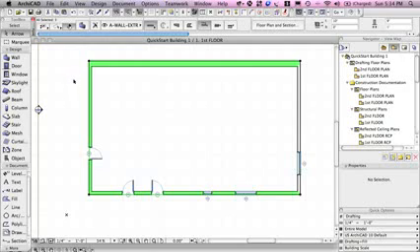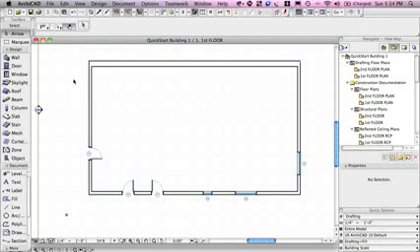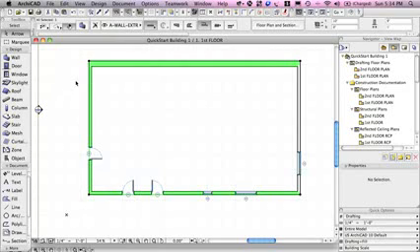So I'll click in empty space to deselect, and now when I want to select here, if I click 2 points, this determines a rectangle, and then I can select things there. In this case, it doesn't make much sense, but sometimes a building has parts of the design on an angle, and this can make it easier to select those elements on a similar angle here.